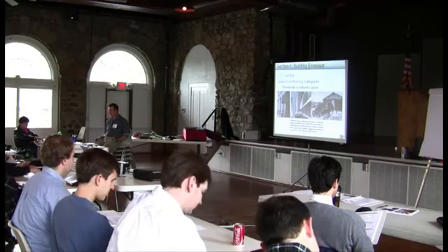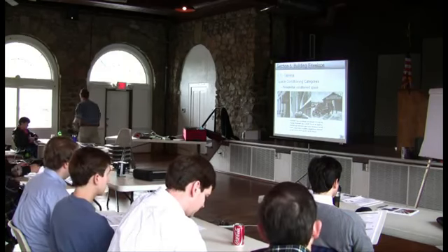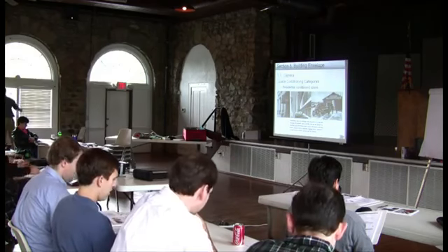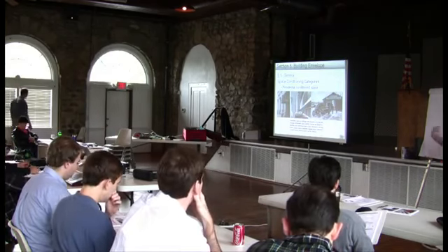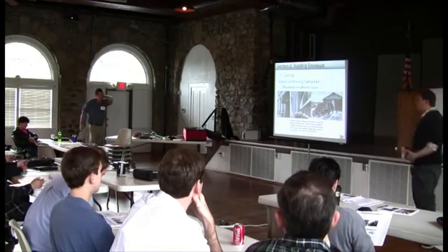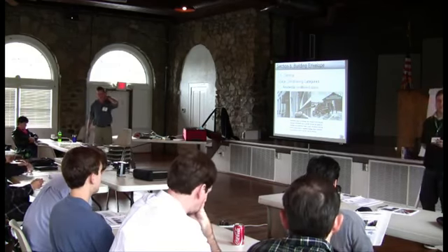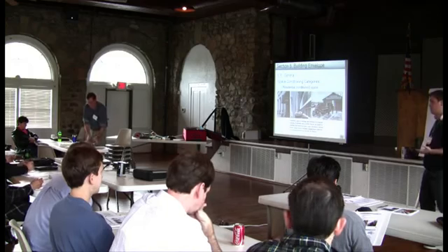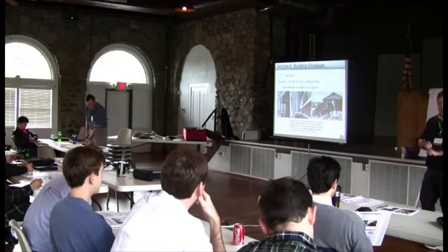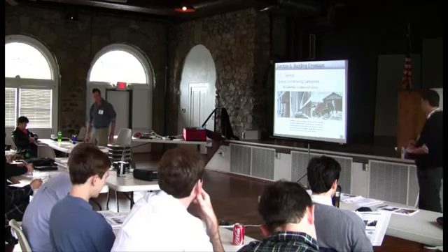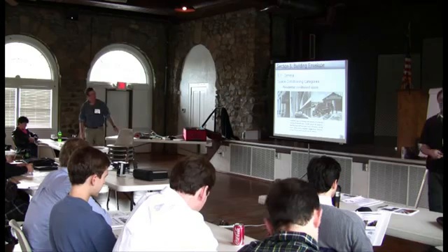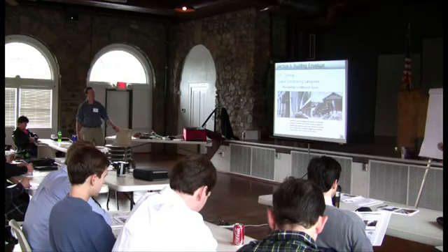Brandon, one more time, residential. Residential. So again, for multifamily low-rise, 3 stories and under, that is the residential code. If it's above 3, if it's 4 stories or more, multifamily, it's kicked in here. Also, other commercial spaces where people essentially stay overnight. So, fire stations, dorms, prisons, frat houses. Those types of things are actually going to fall under the commercial code.